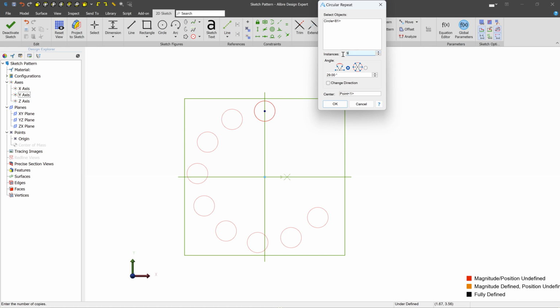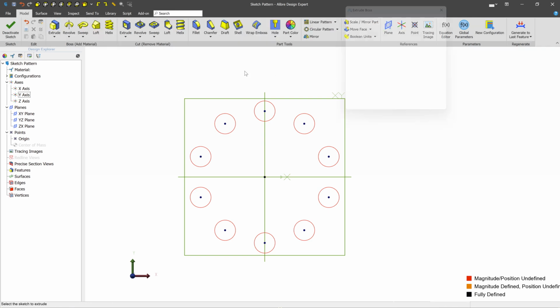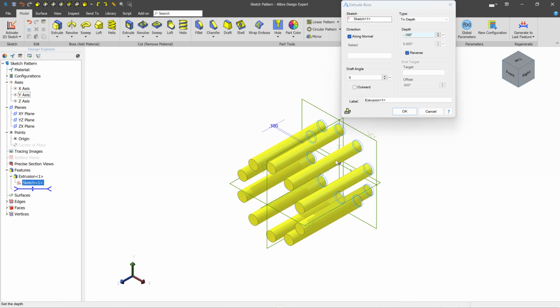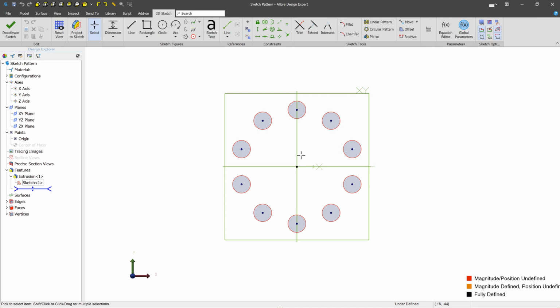What you'll probably end up using a lot more than this, maybe 5, is going to be this one. This says just divide the circle by however many instances we have automatically. And so we don't have to manually set the angle for that. So almost always you're probably going to use this one. Once you have that done, press OK. And our circular pattern is created. Now we could use this, for example, for a feature if we wanted to extrude this. We could do that.